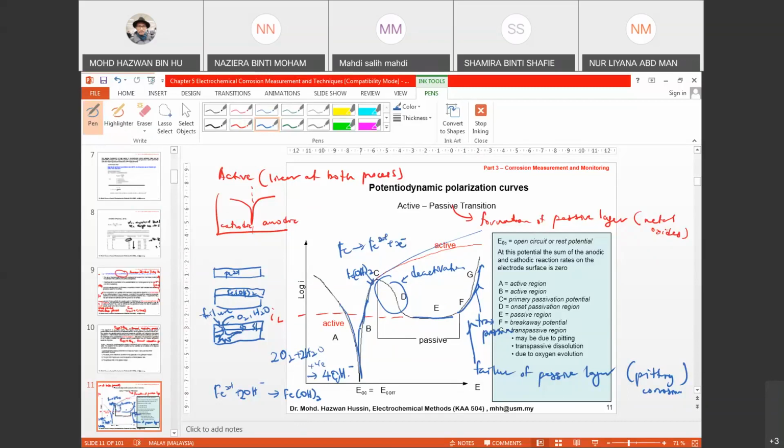Victor, can you repeat the E state? What will happen in E? As I mentioned earlier, when you start to have the formation of rust, like ferrous oxide, hydroxide, and then it starts to thicken, it becomes passive. Then you have a deactivation mode. You have less adsorption, more desorption process of ions. And there's no more changes in current, which results in the so-called limited current density.